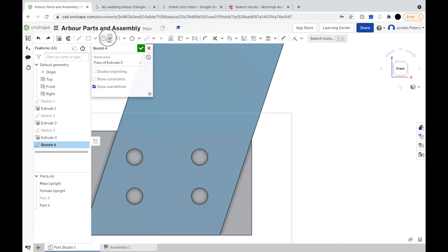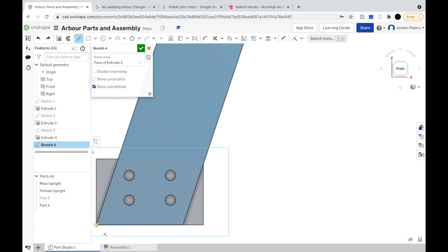All right, so maybe a different type of line, 3-point circle. Nah, won't go. But we do know where the lines need to be, so left click this point, follow along 40 mil there, and then 30 mil upright, and 30 mil again, 50 mil across, 30 mil down, and then 30 mil to the bottom.